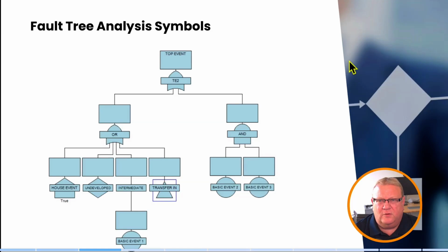Usually we would use simpler methods to model SIFs, but sometimes if you want to model a SIF in a tree structure with other events going on, then you may need to model a SIF within the fault tree itself. We usually start with a process of some sort.